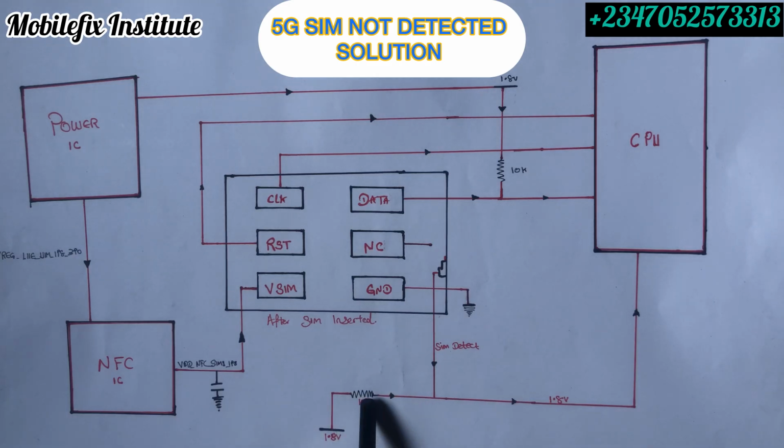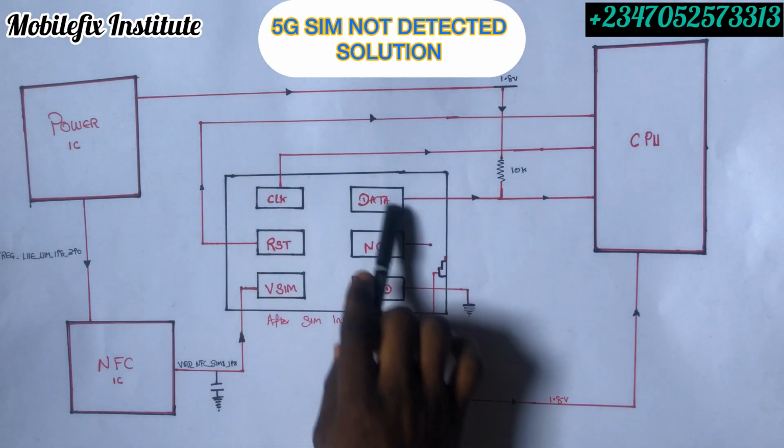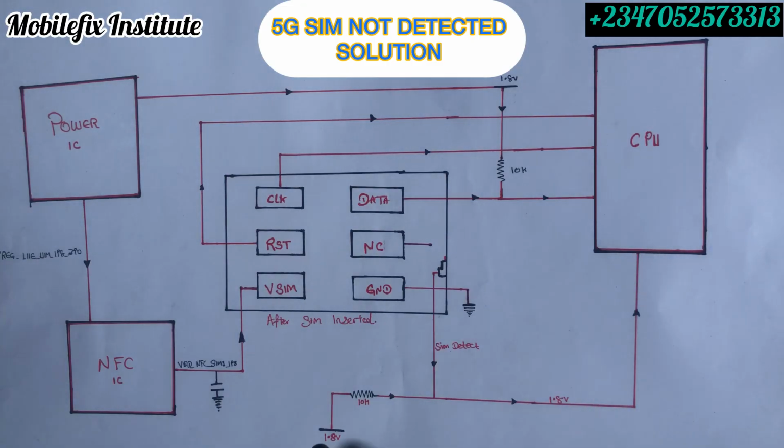Now if this resistor is damaged, your SIM card will not detect, even when these pins are giving you values. So you have to ensure that you test this resistor. It carries 10k ohms in this 5G circuit. So when you locate this resistor, test if you get this 1.8 volts. And before you get this voltage, you have to connect your SIM tray.